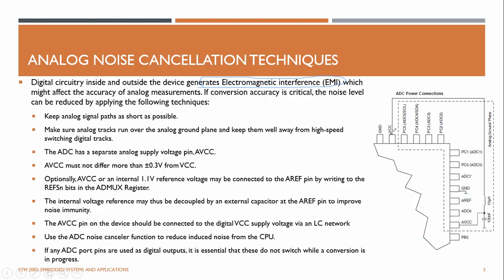The first one is, do not couple this VCC pin directly to your AVCC, right? I have seen many people just coupling this one here. So this is the digital VCC, and this is digital ground, and this is analog VCC, and there's an analog ground, right? So you have to keep them separate.